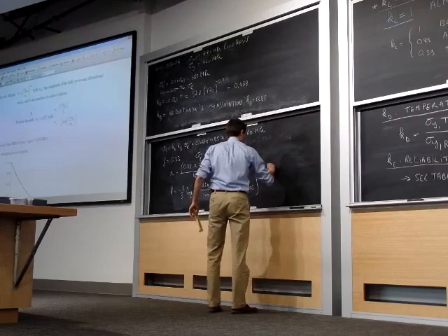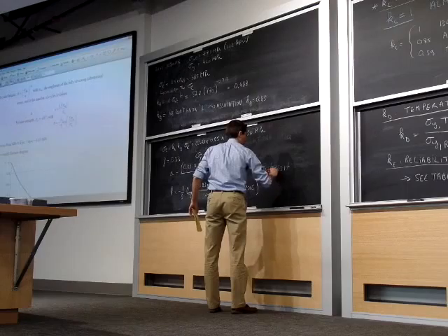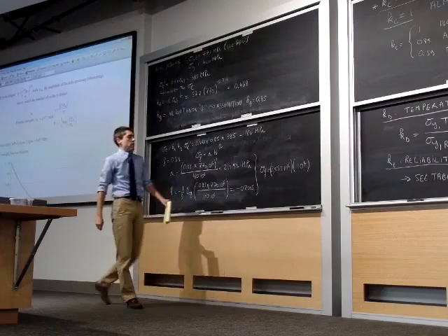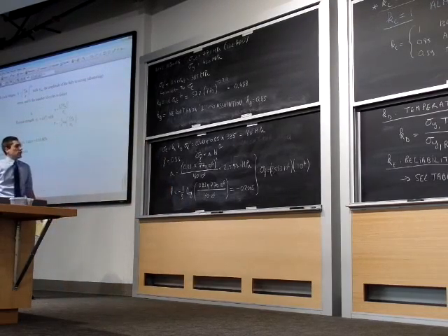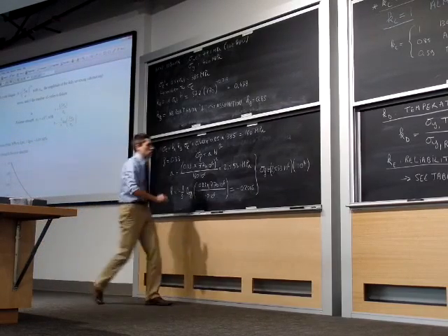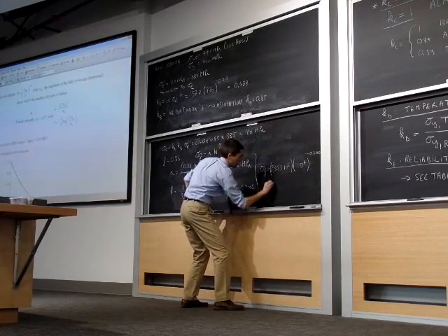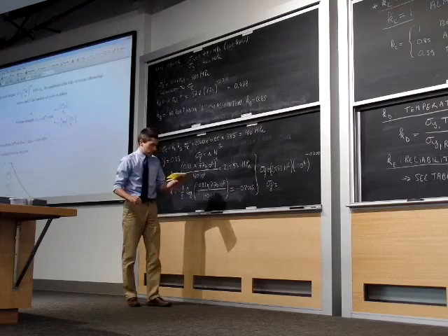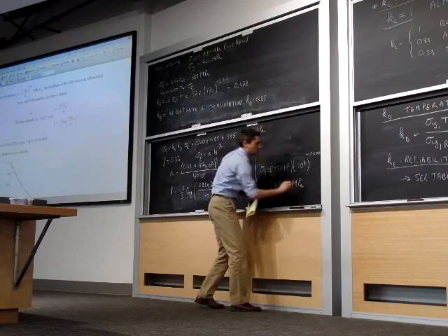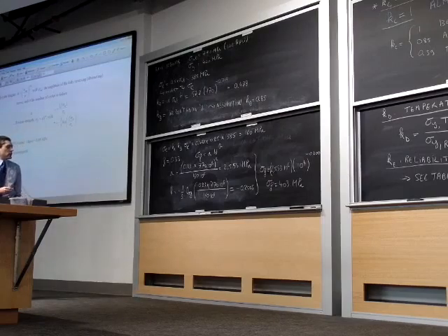Sigma F is going to be equal to 2,553 10 to the power 6 times 10 to the power 4, because that's our n, the life for which we're designing this cantilever beam. And then it needs to be raised to the power b, which we just calculated, minus 0.2005. And so sigma F is equal to 403 megapascal.